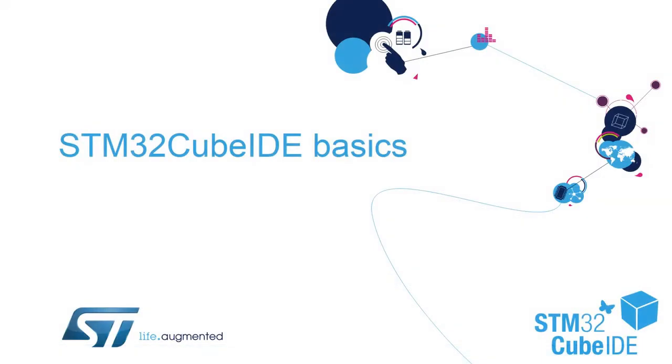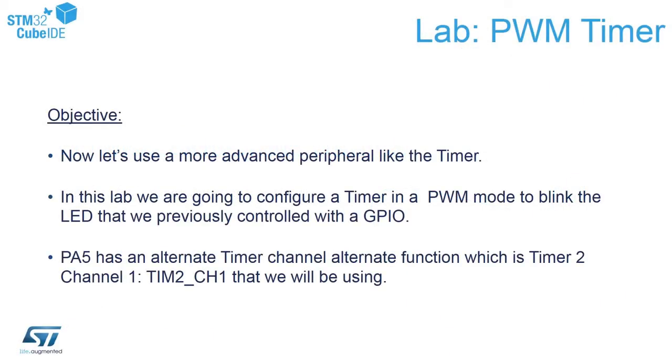Hello and welcome to our STM32CubeIDE Basics training session. In this part, we will use a timer to control our green LED in so-called PWM generation mode. The objective of this session is to configure the timer in a PWM mode to blink the green LED. So instead of using the software code, we will let the timer do the job and toggle the LED. This time we'll use PA5 as an alternate function, and we will let timer channel 1 control it.